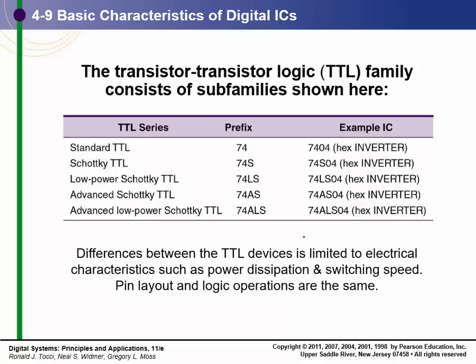When we look at an S part, it's a high speed. Now, as a technician, if you're repairing something, sometimes staying within the same family makes a difference. Sometimes it does not. If the engineer that designed the circuit did a good job and used synchronous design techniques and did not push the speed limit of the circuit, of the components, then it doesn't necessarily matter that much.